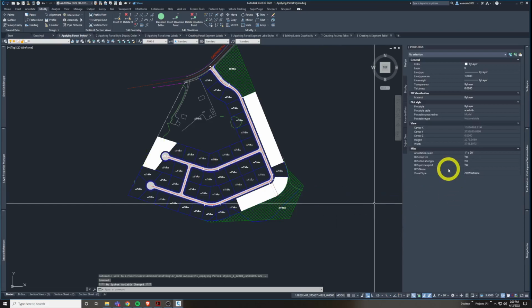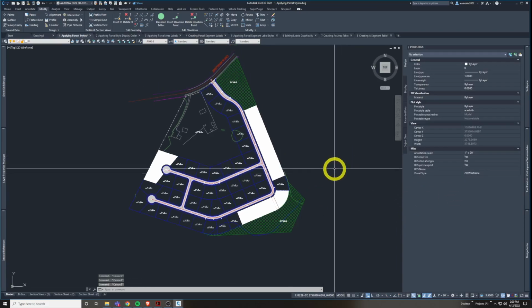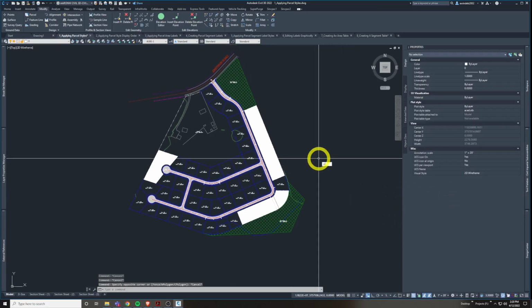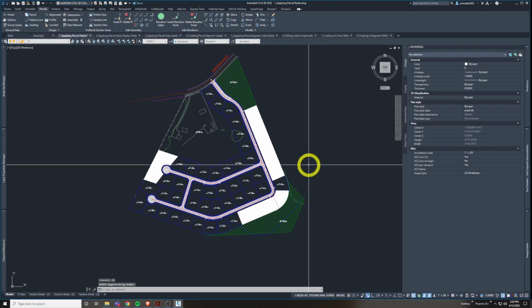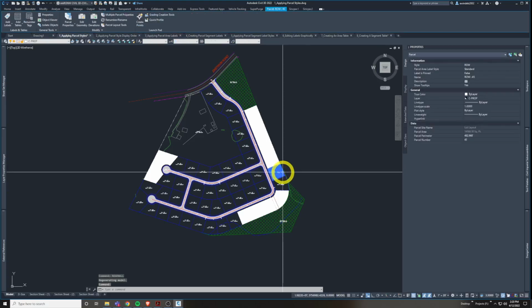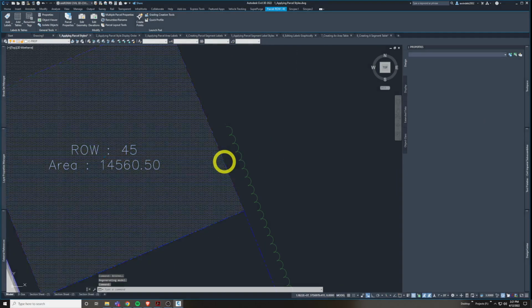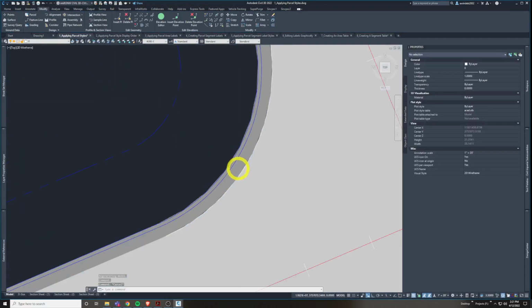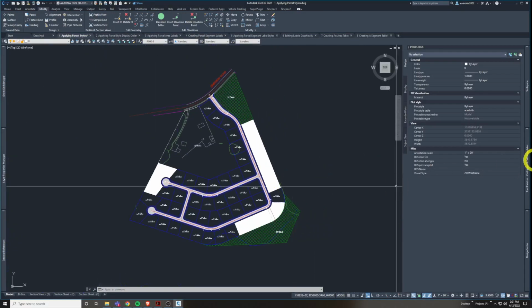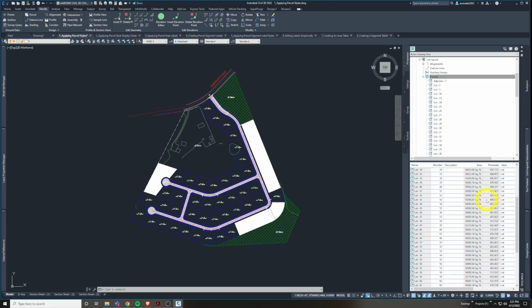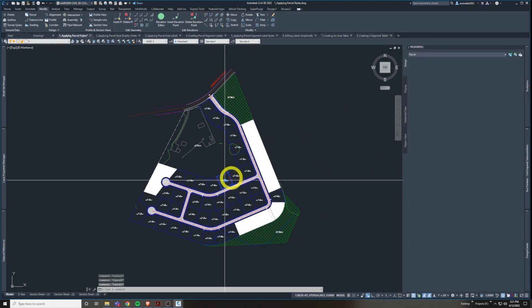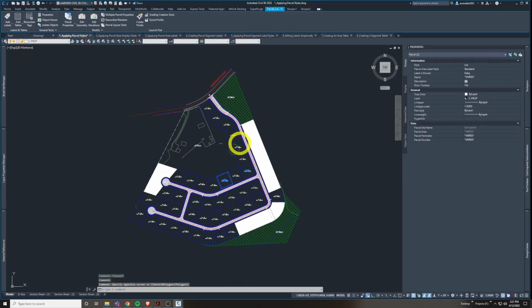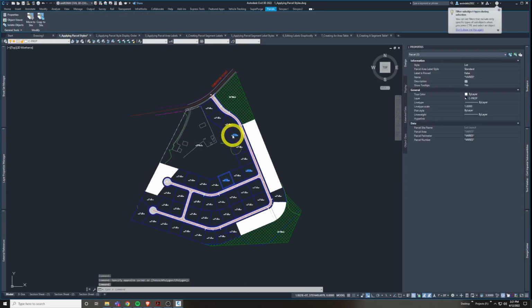It takes a minute. It freaks out for a second. I changed a few of them to the right-of-way style. I'm going to hit regen all or regen. And I changed some of these to a right-of-way style like this, similar to this style. So cool ways you can surgically grab them here, or by getting creative in your selection set here, picking them manually or using select similar.